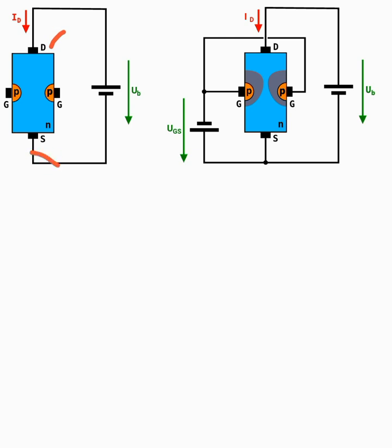Across drain and source I apply a voltage source with the positive connected to the drain and the negative of the battery connected to the source. As a result, the N-type semiconductor, which is the blue region, acts as a resistor through which this voltage source supplies a current, and that current flows from drain to source as indicated by the direction of the current.